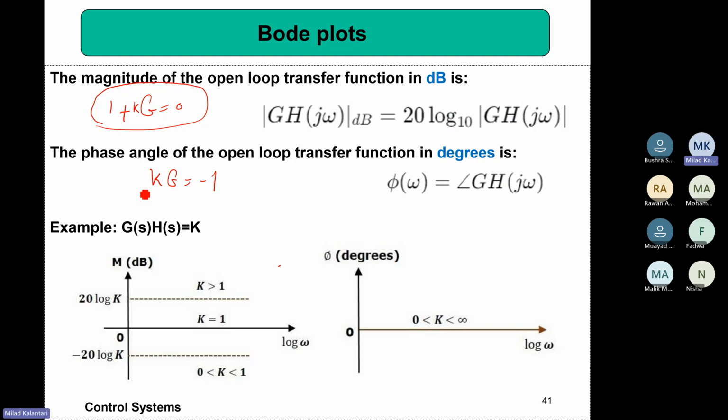If this situation happens at a certain frequency, because now we are exciting with a sinusoid, it means that frequency is a pole of the system. And since it is imaginary, it tends to be unstable because it's right on the imaginary axis, right?